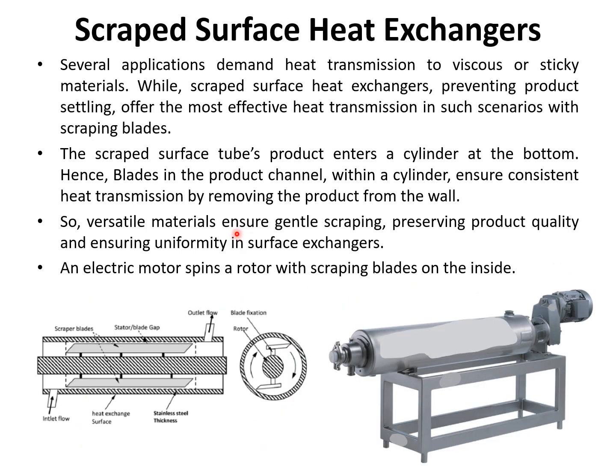Okay, so moving ahead with the scraped surface heat exchanger. What is scraped surface? In your home you have butter, you have mayonnaise, right? This exchanger is used to manufacture butter. The medium will flow, and you have a scraper. In the middle is the rotor, which moves the scraper, and on the outer surface you have the heating or cooling medium. On the surface, your medium will get cooled or heated, and you will get it out from here.